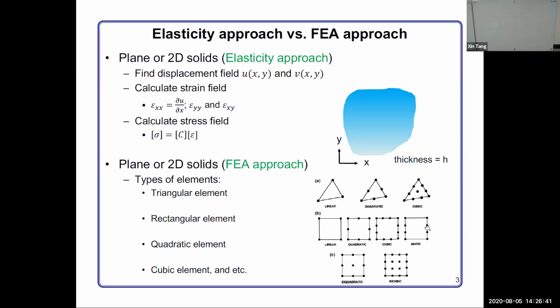The reason why we change the nodes in all those elements is because in the finite element, all the solutions actually exist in the nodes. So the element actually contains all the information, stress, strain, and displacement, all on the nodes. And then for points not on the nodes, like on those edges or in the center, we do the fitting, we do the interpolation to get approximate results.